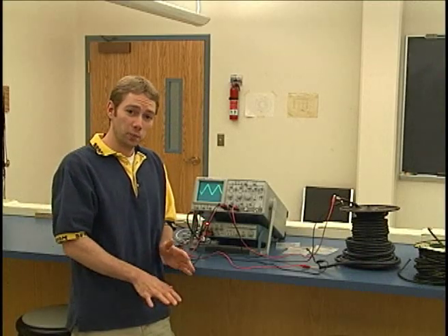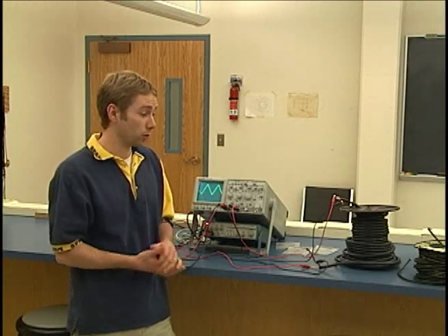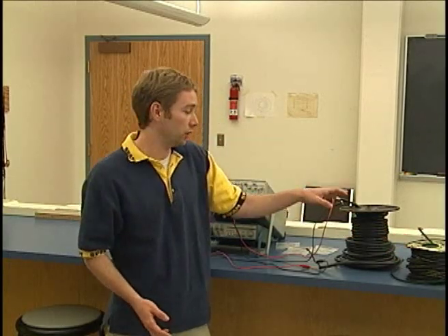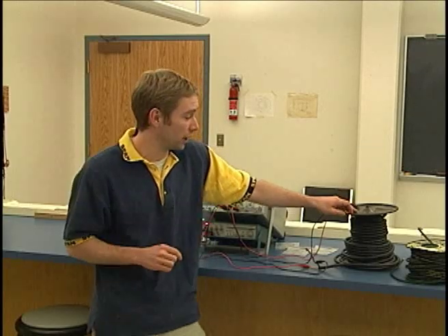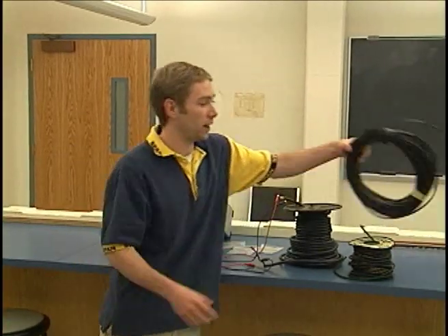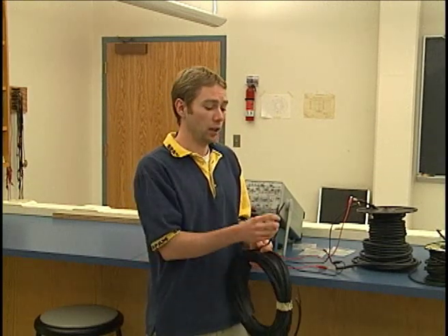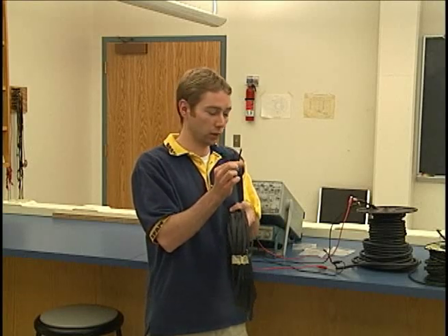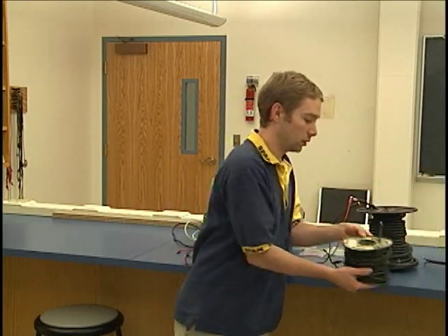All right, so for the next part of our lab, we are going to be measuring the speed of light, or electromagnetic radiation, through various types of cable. In this particular lab, we have RG62 cable, RG58, which you might see as the RG8 cable, that's the same one for our lab, and you may or may not have this antenna cable as well. Now the differences between these cables: the antenna cable will have these two wires that are going to be next to each other like this, and the other types of cable are just going to be coaxial cable.